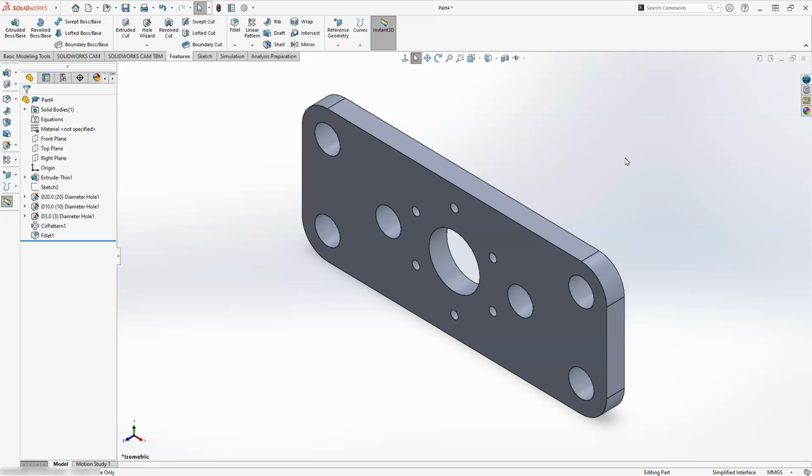All right, so thank you for watching this video. Hopefully this was kind of informative to you. As you can see, if you have a lot of holes on it, it's good sometimes just to put it in one sketch. The one caution I will tell you is that try not to have that sketch highlighted already and then select the hole command, as it will look at all of those endpoints as points to place those holes on, and you saw me do that.